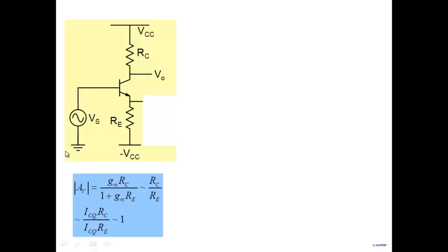So if you eliminate the capacitor directly from here, so we don't use any capacitors, I end up not getting gain. I can't build large gain in my circuit. Gain would be very close to 1. So the issue is that I have to get rid of the capacitor here, because this capacitor I can't build on a piece of silicon. I have to get rid of it.